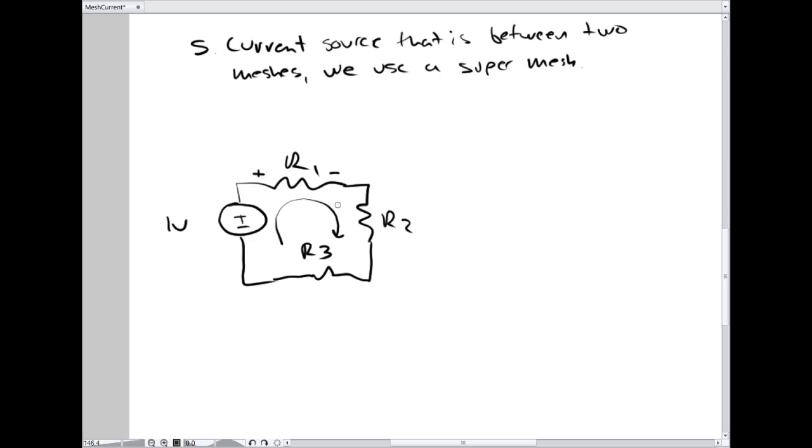If we define a current all the way around a loop, as long as that current follows the voltage drop for all the voltages around the loop, then those voltages would be lined up correctly for Kirchhoff's voltage law to work. And that is, plus minus, plus minus, plus minus. So this way of defining things is in agreement with that. This makes it such that the voltage source should also be defined plus minus, with the plus upstream and the minus downstream. And in this particular case, the polarity is the reverse of that, so I need a minus sign.